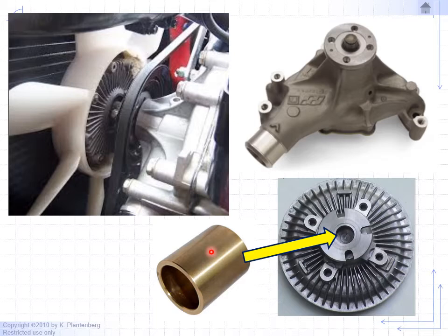You can, for example, tell them as long as the diameter is within 1.001 and 0.999 inches in diameter, then it's acceptable. So again, you mass produce parts, but you have to give the manufacturer some wiggle room as to how much they can be off by, and yet make it acceptable to replace an old part on the vehicle, for example. Next slide.